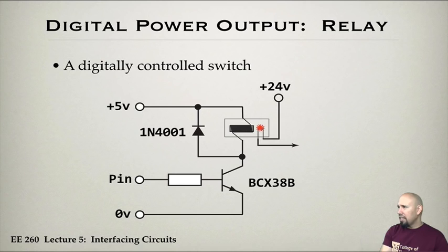What the magnet does is it has these 2 contacts, and usually one of them, this one over here, is magnetic. When the magnet turns on, this one gets pulled over and touches the other one. So you have these 2 contacts and a magnet, and when the magnet turns on, this one gets pulled down and they touch. They make contact. And when the magnet turns off, it releases. These contacts can handle more current than these contacts, which can handle more current than this pin. So it's like stages that allow us to do this.